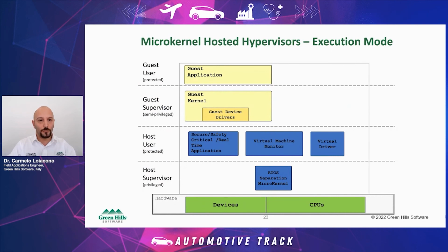This is the final architecture that we see, where there is the separation microkernel running in supervisor mode. Then we see that there are critical real-time applications, secure and safety critical applications, running in user mode, but still user mode for the microkernel, which means those are native microkernel applications. We see the virtual machine monitor and the virtual driver.